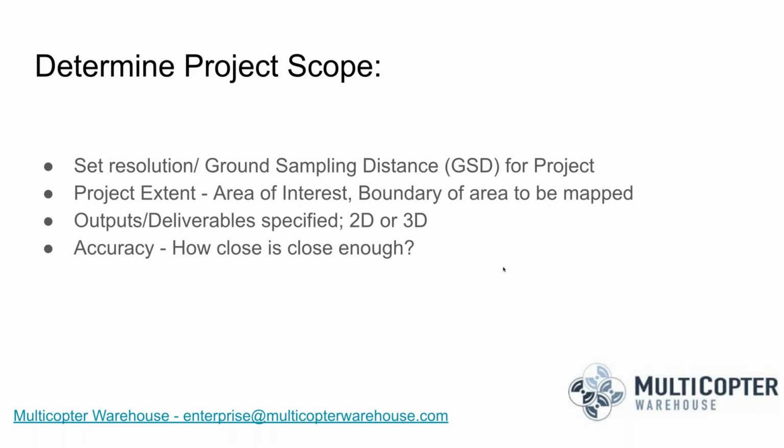And then also you want to make sure you're really properly defining the project extent. My preferred way of doing that is to have the customer or the person requesting the map provide me with a KML file that can be generated off of Google Earth. That way we know ahead of time clearly what the delineation of the project boundaries are. There's nothing worse than going out and doing a project and trying to give it to the client when he says, oh, well, I also needed this area just over here.